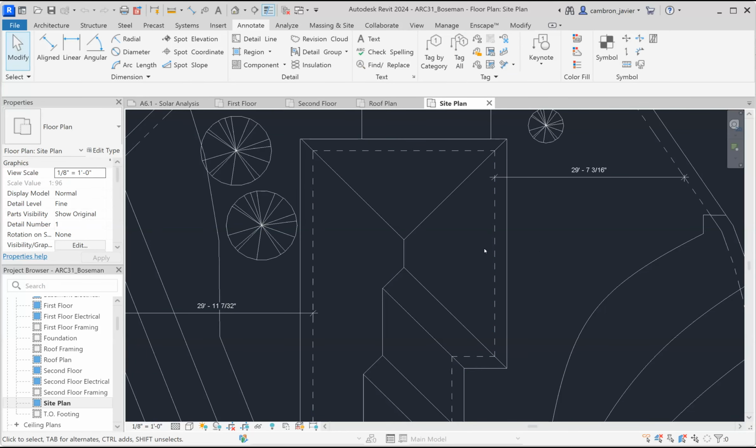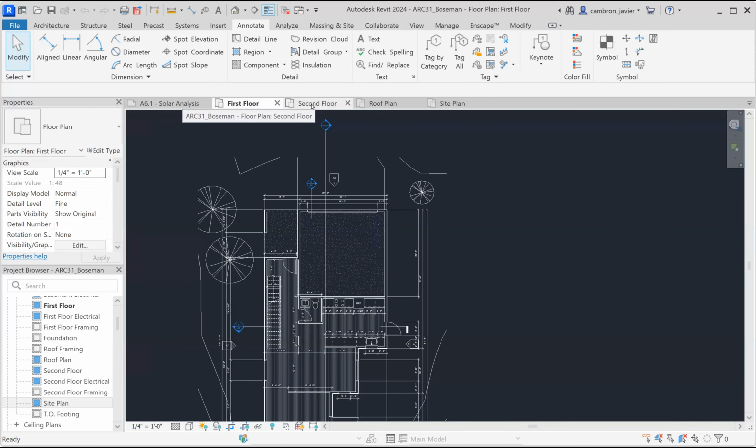Now, that's not to say that Revit doesn't have that capability. It does, but sometimes it's just easier to draw it two-dimensionally than it would be to model it out three-dimensionally, create a family, create a profile, extrusions, things like that. So instead, we will use the detail line, okay, or our detail tools.